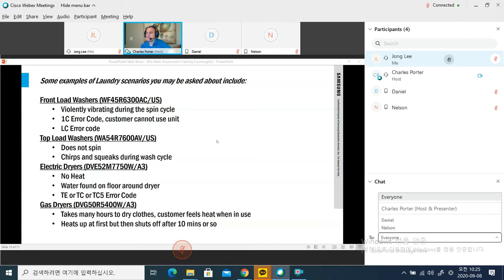And other than that, just a good physical inspection. Popping that back access plate off, checking the motor, make sure nothing is damaged. Check especially on an older unit that's already 2-3 years old or older, that's maybe been used quite a bit. Check the wash drum itself or the wash basket. Make sure it's not wobbly.